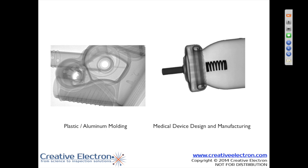But essentially, you want to make sure that your molds are set up properly and that with the flashing, you're pulling away any porosity or voiding. So voiding in aluminum components is really a pretty important key in making aluminum components. You don't want to machine a component and then find that after you've machined it and threaded the component that you have bores that have holes. You can't seal them up with gaskets and you can't seal them with O-rings. So aluminum and plastic molding is a big one.